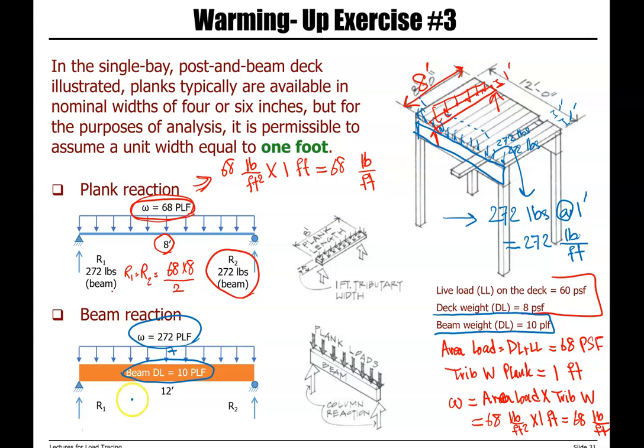Now we can calculate the reactions. Again, simply supported beam, symmetric, reactions are equal to each other, and they're equal to 272 plus 10 times total length. The span length is 12 feet.